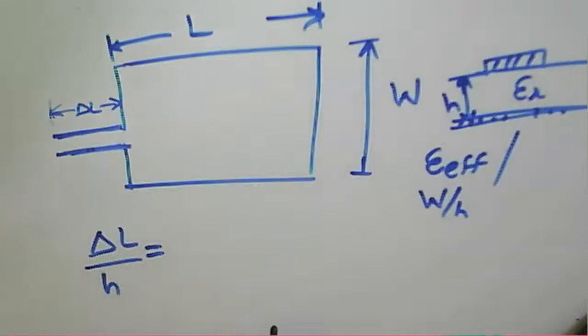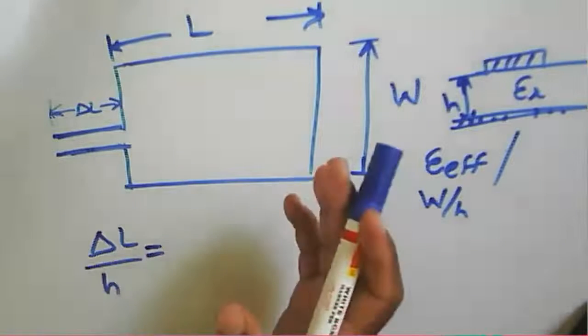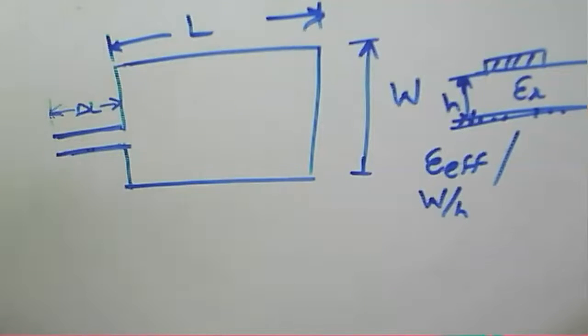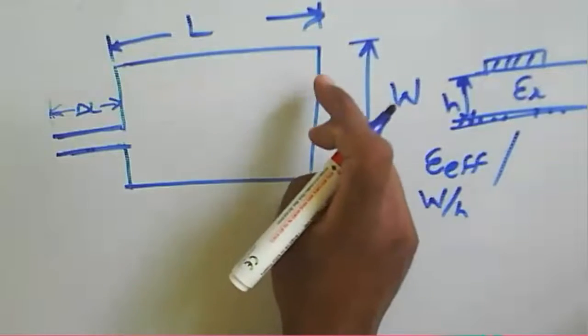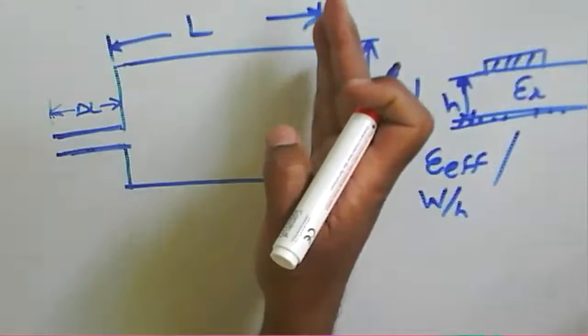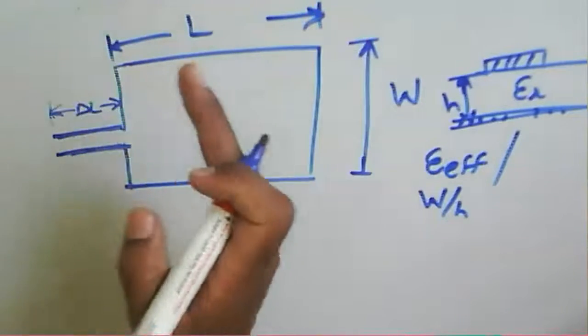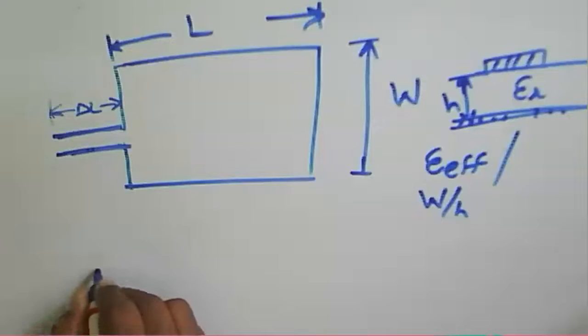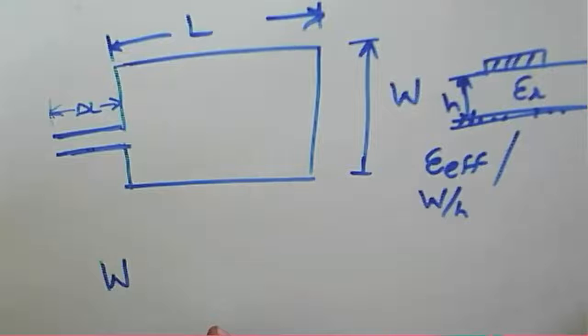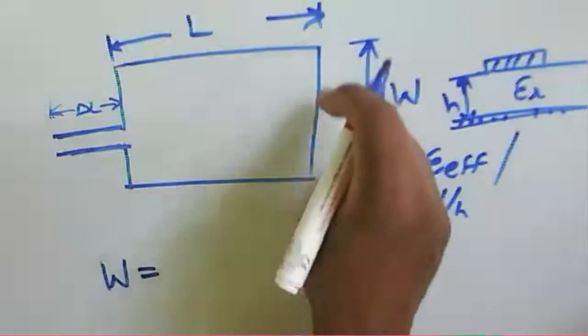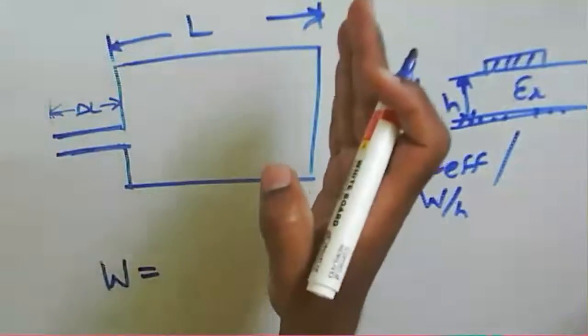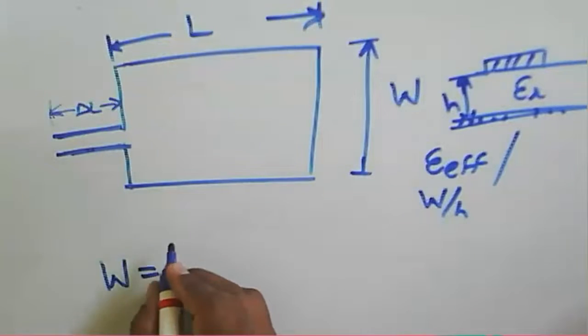So that's about the length. But whenever we design a microstrip antenna, we need to know the value of this W here, because this one acts as the radiator. This is the radiating slot. So for an efficient radiator, we need to find the width of this particular patch, because it acts as a radiator. Consider it in terms of a parallel dipole. Likewise,